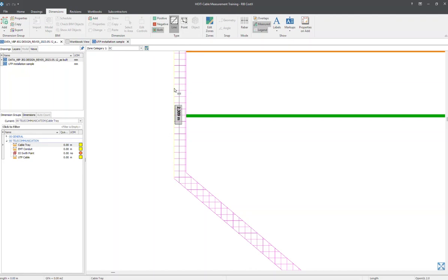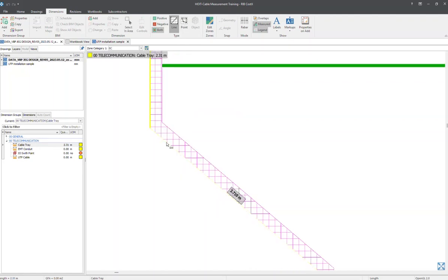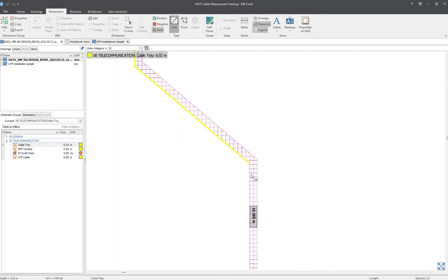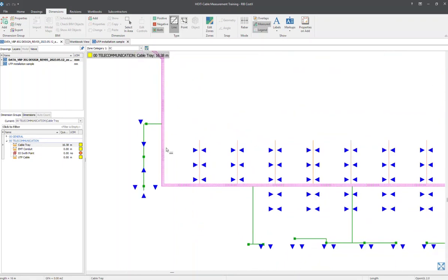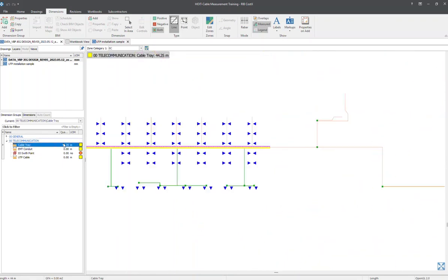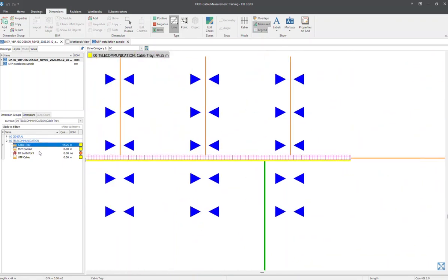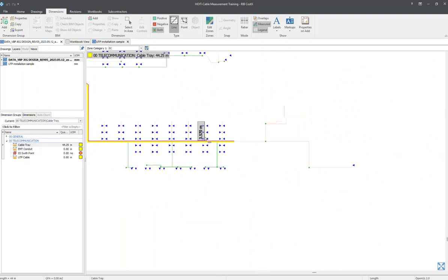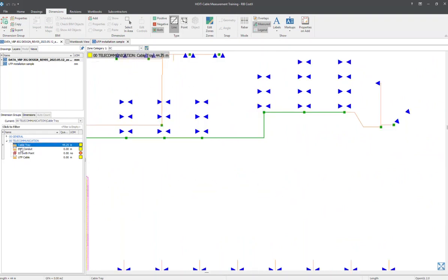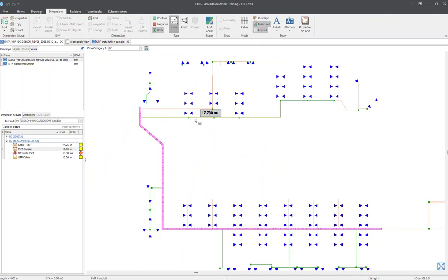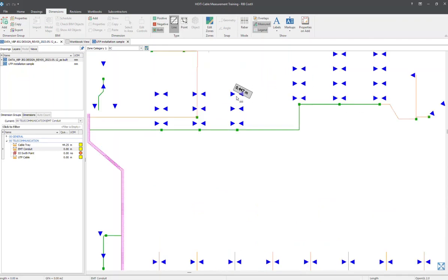the layers itself. So I just click it, and click the second one and the third one, and direct all the way until the end of this cable tray. Now I have 44.25 meters for the cable tray. Okay, now let's go to the next element, which is the EMT conduit. So the EMT conduit is basically all the lines here except for the blue triangle.